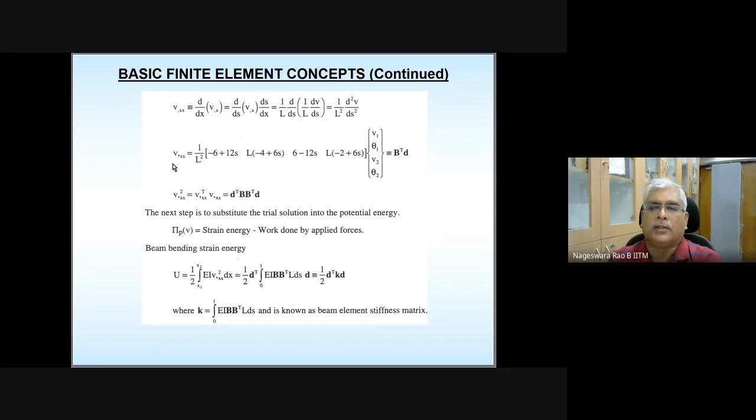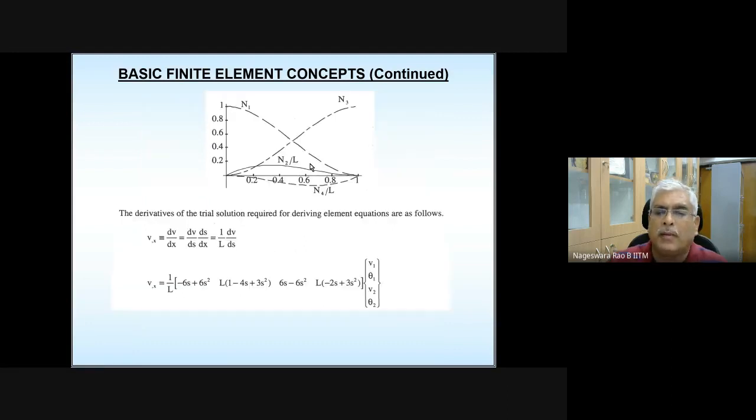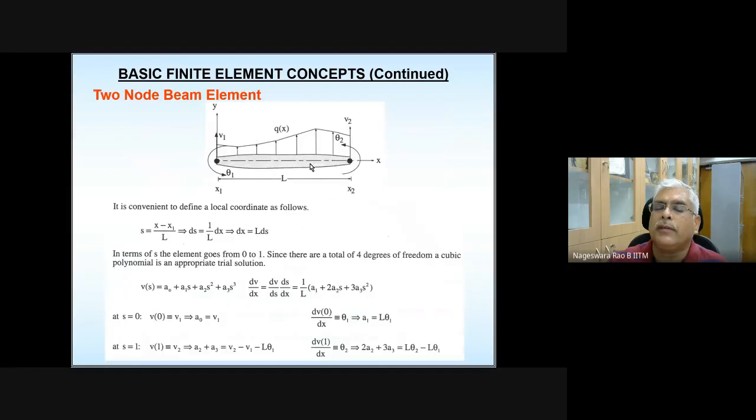So if the bending moment has higher order variation, then you may have a problem in capturing that. You need to keep that in mind. Anyway, you will have a better feel for it when you are solving a numerical example. So this two-node beam element may not be able to give you exact results for all types of loads.